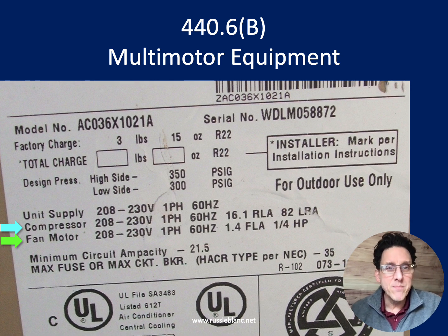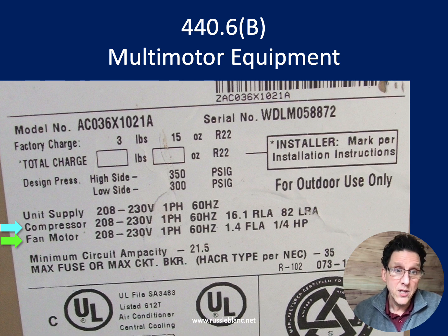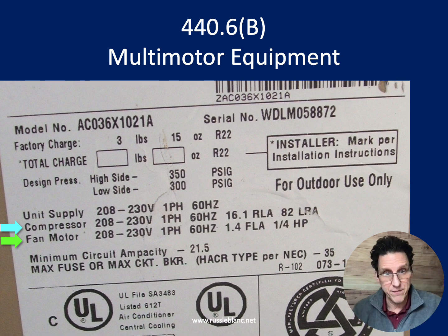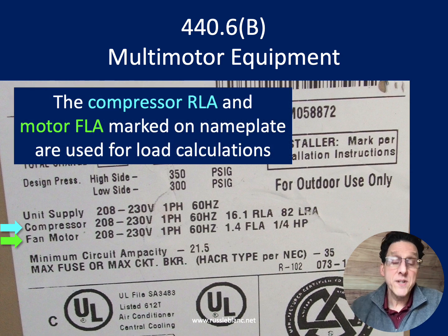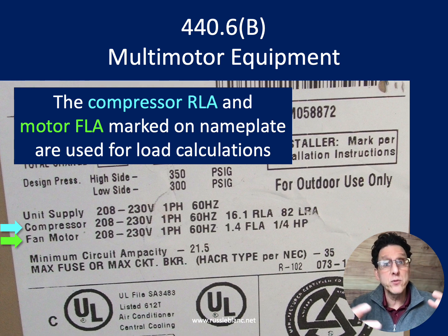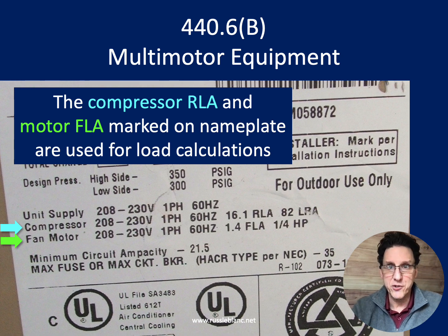Okay, when it comes to multi-motor equipment, we're supposed to follow whatever 440.6(B) says. All right, so here's a nameplate for an air conditioning unit, and you can see the blue and green arrow there. There are two motors. One's a compressor motor, a hermetic refrigerant motor compressor, and then the other is a fan motor, the evaporator fan. So there's two motors, or a compressor and a motor. Now 440.6(B) says we're supposed to use the compressor RLA and the motor FLA marked on the equipment nameplate. We're supposed to use that for load calculations.